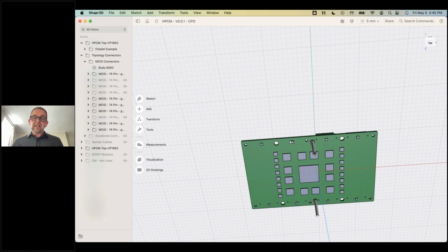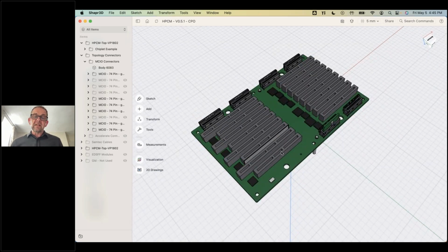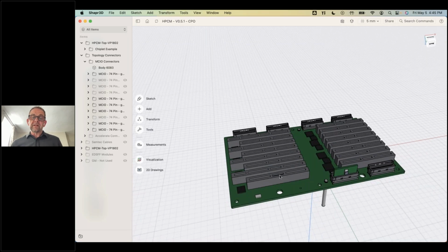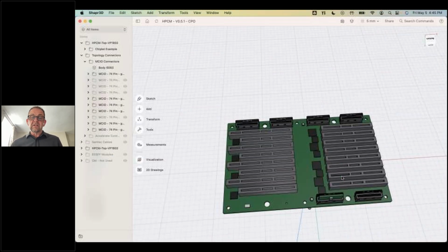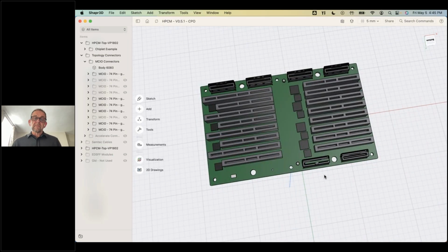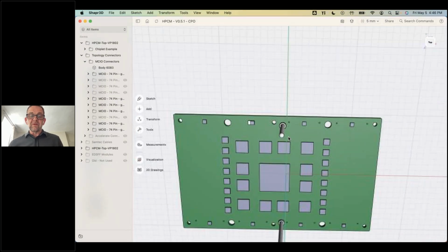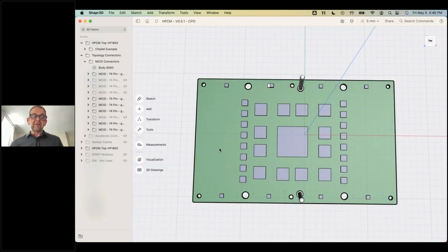Okay. And then now you will need power to power these media. So the 48 volts will get transformed down to 12 volts, and the 12 volts will feed these modules here. And there's something I'd love to do in the 12 volt world if we could get the standards people to change. And so those are the little chips right there in between, that's what transforms the power from 48 to 12? So no, sorry. These are sideband management chips, which I'm working with Lattice on. That would be more of the fabric management. But no, the power, sorry, I've not shown the power. I showed it in the PowerPoint, but it would be in these regions here, like it is on a traditional OEM. Or you could potentially put power between the devices if it made sense to. So the point of load power is not shown here.